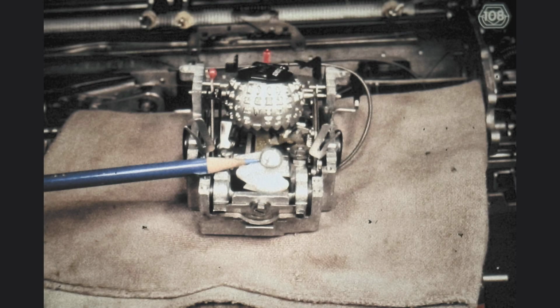Notice this wiper washer around the screw, which functions as the pivot point for the tilt pulley sector. This wiper washer should be kept impregnated with light typewriter oil so as to always keep the pivot point for the tilt pulley sector properly lubricated. Wear on this hub of the tilt pulley can affect the tilt detenting and, indirectly, the rotate detenting, causing poor alignment. The same criteria apply to the wiper washers around the print shaft.